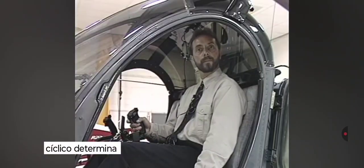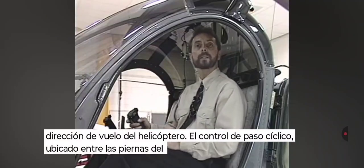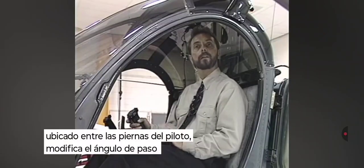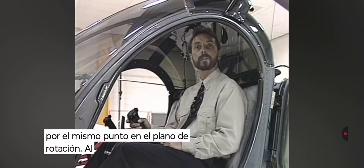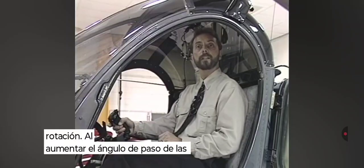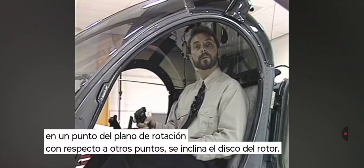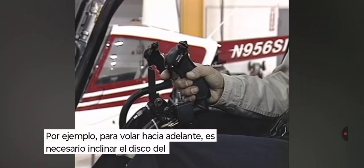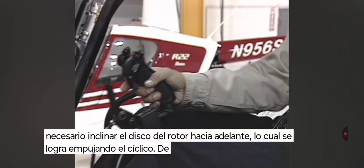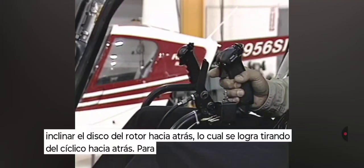The cyclic determines the helicopter's direction of travel. The cyclic pitch control, located between the pilot's legs, changes the pitch angle of each of the rotor blades one at a time as they pass through the same point in the plane of rotor rotation. Increasing the pitch angle of the blades at one point in the plane of rotation relative to other points tilts the rotor disc. For example, if I want to fly forward, I need to tilt the rotor disc forward, and I do this by pushing the cyclic. Likewise, if I want to move aft, I need to tilt the rotor disc aft, and I do that by pulling back on the cyclic.